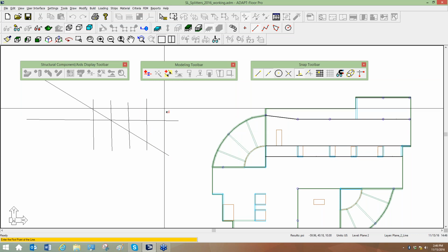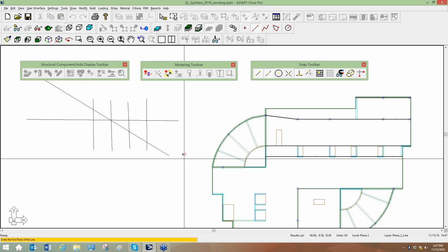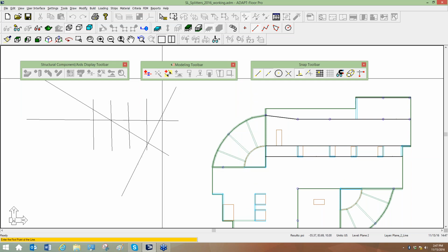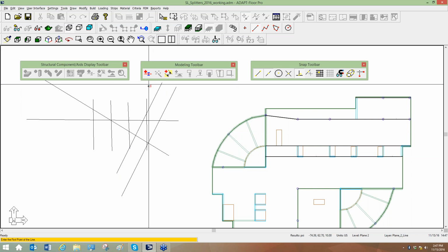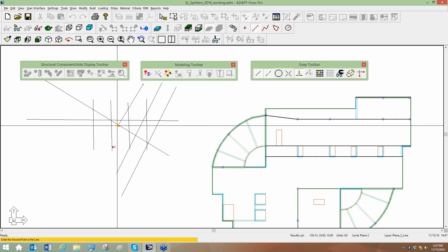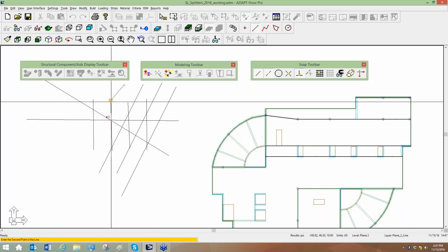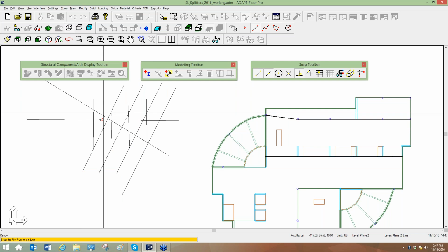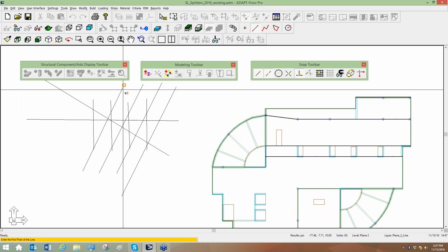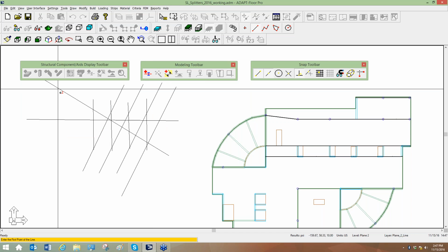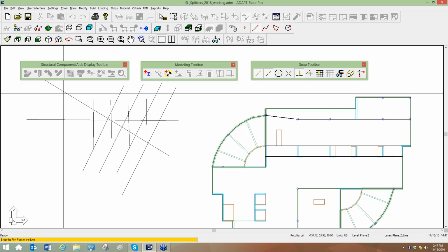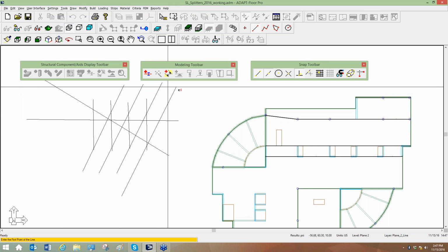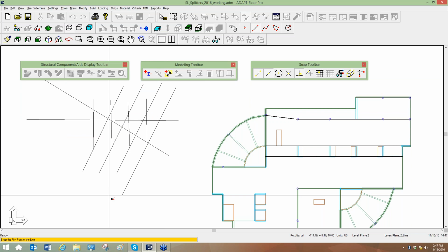Now, as an argument to that, if I have a banded tendon that looks like that, but I also have distributed tendons that look like this, those are also intersecting these design cuts. So not only will these design cuts that are in the X direction here be affected by the banded tendons, but they're also being affected now by the distributed tendons.